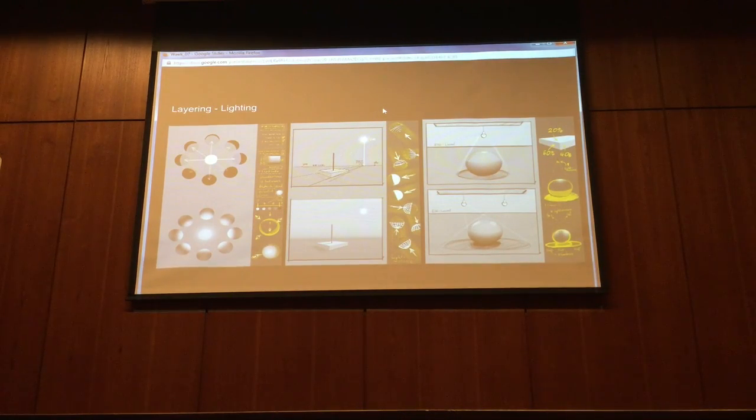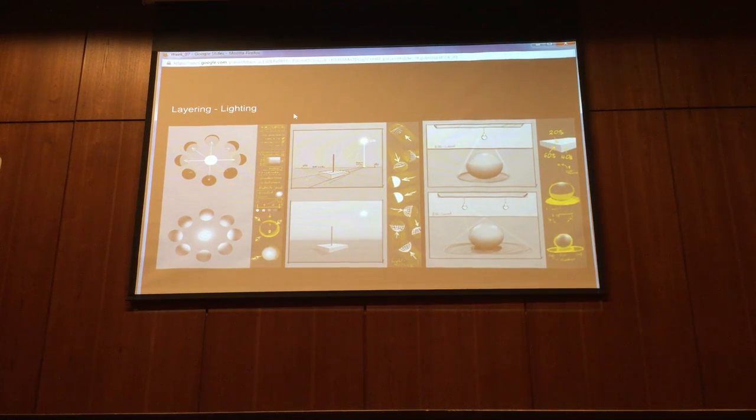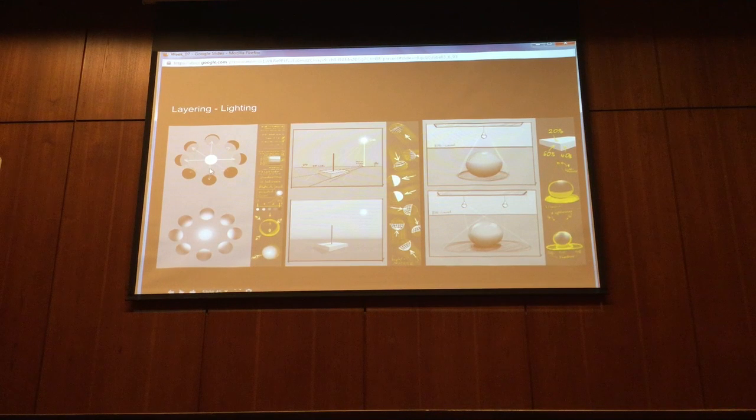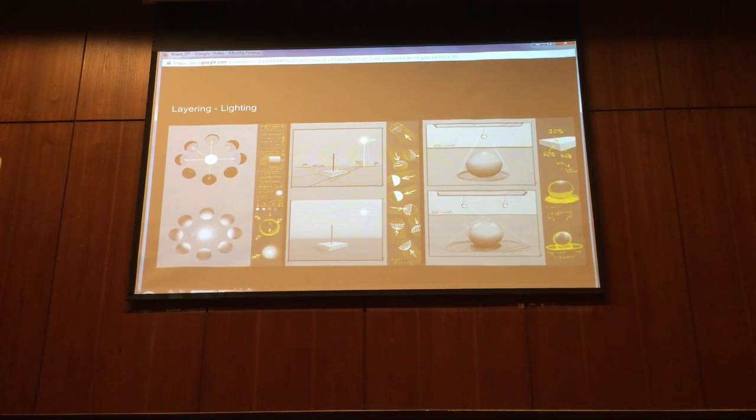Another way of breaking out light. So, type in light, Rhino, right? There's a panel of different options. There's point lights. There's spherical light. There's directional lights, which is kind of the sun. There's tube lights. There's planes. All of those types of stuff, right? Anything you see in this type of environment, it's easy to recreate. So you can have the object, the point light itself, and you can see all the different shadows that are being cast on there from how close they are to the actual surface, right? So that's the emissive material.